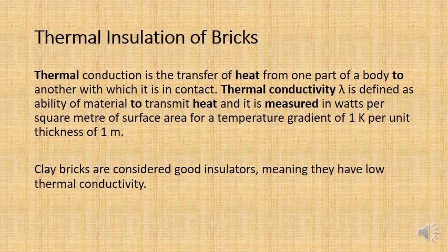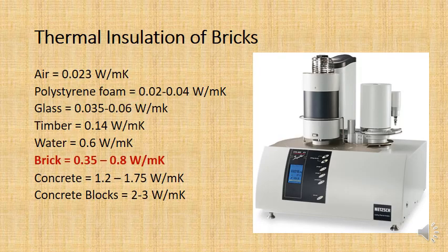The smaller that number, the better the thermal insulation, and clay bricks are considered good insulators. As I said, it's around 0.5 watts per meter Kelvin. It's very low. So let's just look at this for comparison. Air has quite a low conductivity value, 0.023 watts per meter Kelvin.